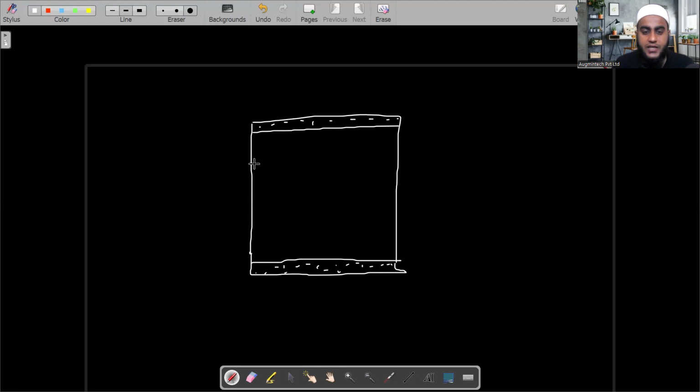Inside the room, if you have a false ceiling, just draw the false ceiling. The height from FFL to this is called the false ceiling height, FCH. In our situation, it is given as 12 feet. From this point, this portion is called the bottom of slab, BOS, or also the soffit of slab.